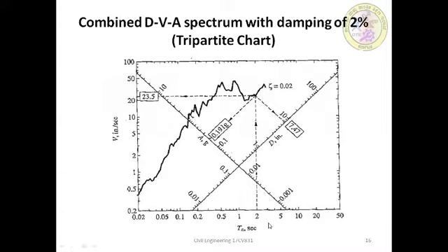Since the peak ground acceleration, velocity, and displacement for the various earthquake records differ, the computed response cannot be averaged on an absolute basis, so normalization is carried out by dividing the spectral ordinates by the peak ground acceleration, velocity, and displacement for the corresponding region of the spectrum.